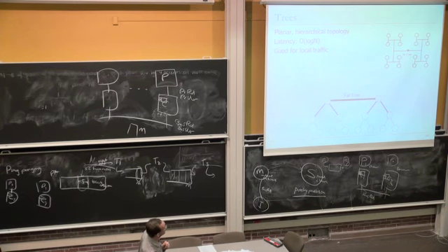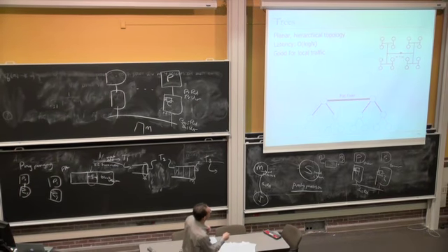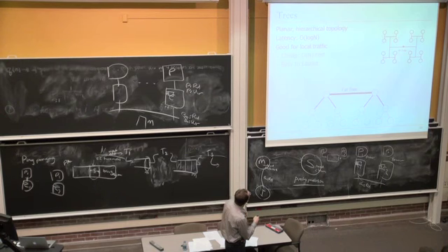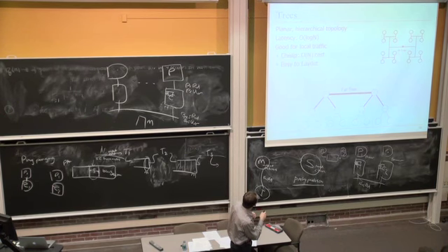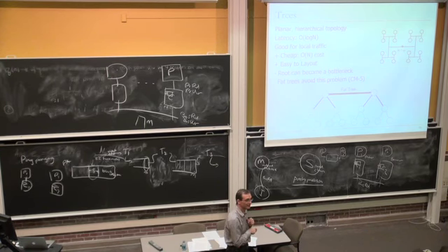It's good for local traffic, if you will. For example, if you have 2 nodes communicating here, it's nice, right? Because you have these connections that are close by. Cost is cheap, O(n) again, easy to lay out. The problem is the root can become a bottleneck, right? If you have a lot of communication happening between these 2 different sides of the tree, well, there's another route. You could do that over here. Then that route will become the bottleneck, right?